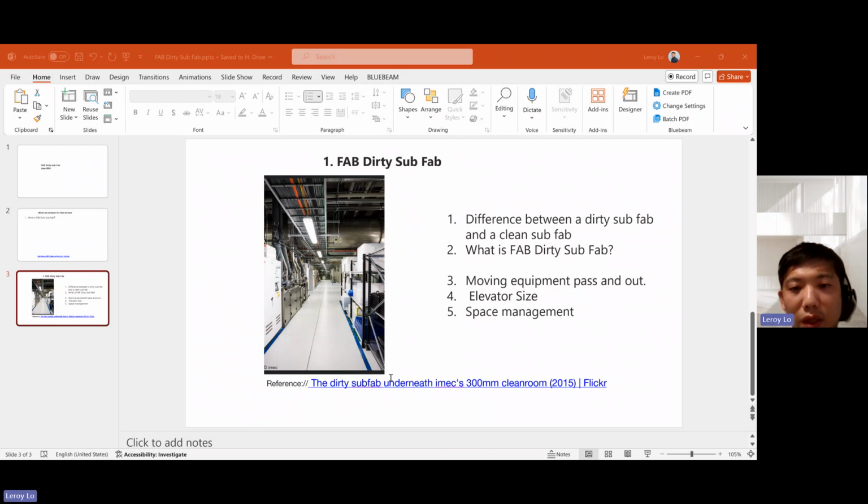And number three, moving equipment in and out. Depending on the foundry design, let's say you have six tanks that do the same identical work. That means installing two or three and leaving some space for the others to come later. So moving paths will be very critical to identify for all the facility equipment, and they will be the same for the boiler and other equipment too.